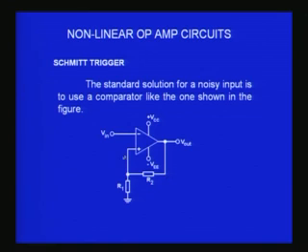So this is actually positive feedback, as you can see, since from the output I am giving to the plus side. So it is called a regenerative comparator. Now because I have connected it like this, something very important and very simple is going to happen, and that is V output will decide what the threshold or the reference voltage here is.